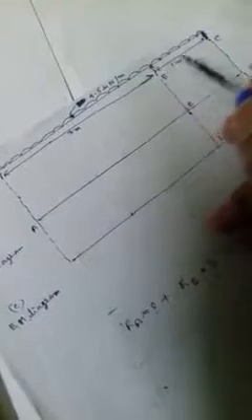So this is equal to the total force from these reactions. So the total force will be as 4.5, the value of UDL, up to a distance of 4 meter, 3 plus 1 meter, 4 meter. As per the rule for UDL, we take the midpoint of the UDL. So the midpoint of length 4 meter will be 2, so into 2. This is the value of UDL and this is the distance.